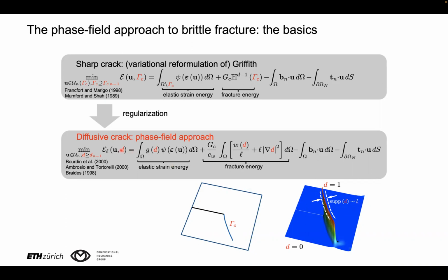Now let's look at the regularized functional here, which is now no longer a function of u and Gamma C, but of u and d. Once again, we have three contributions to this energy: the elastic strain energy, which now includes this degradation function g(d), which is coupling the two fields with each other and is degrading the elastic strain energy as a result of the damage.